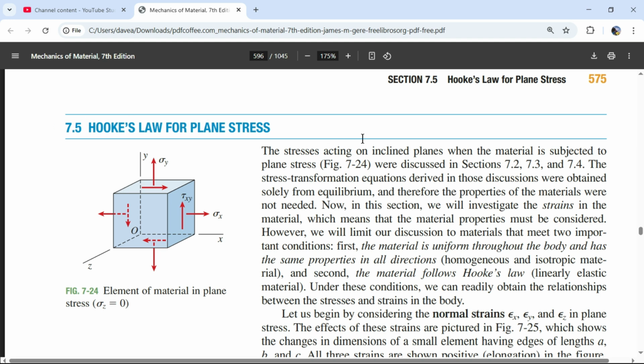For biaxial stress, if this is a bar and I'm yanking on it, I can really just cut at any angle, and then whatever this surface is, I can just say we have a normal force and a shear force, and that shear force is just going to be the average over that surface. But if I say that's the shear force over that surface, then I'm getting an average shear stress. So if I had biaxial stress and I'm cutting at a 45 on this surface, I'm getting an average shear stress if I calculate it that way. But that shear stress is going to be actually zero at the very ends, and it's going to be a maximum in the middle.